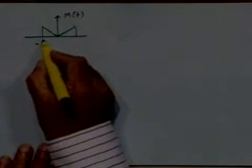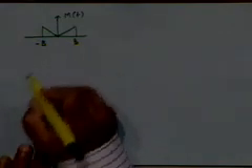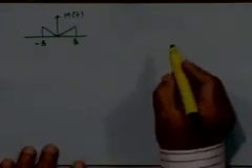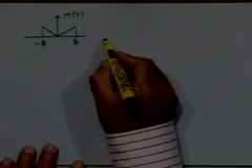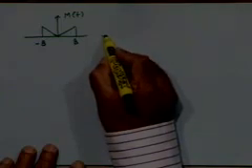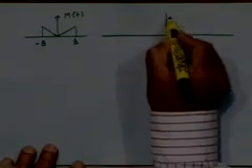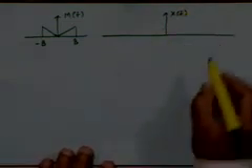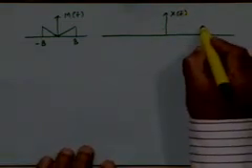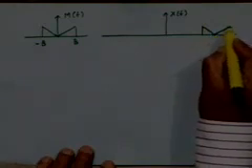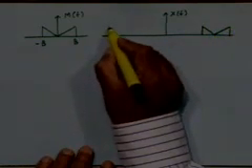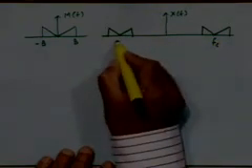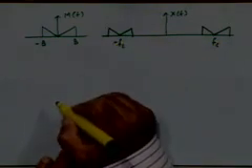So suppose your message waveform has a spectrum between minus B to plus B, as a Fourier transform which is non-zero over this range. Then your modulated spectrum X of f, the spectrum of the modulated signal in this case, would be like this, where this is around fc and this is around minus fc, right?